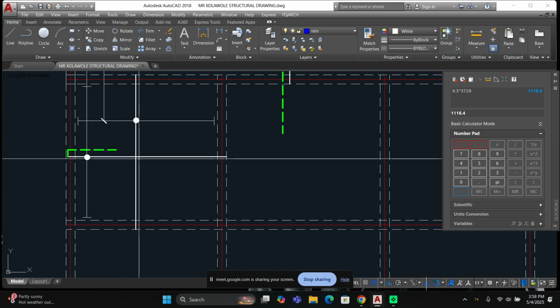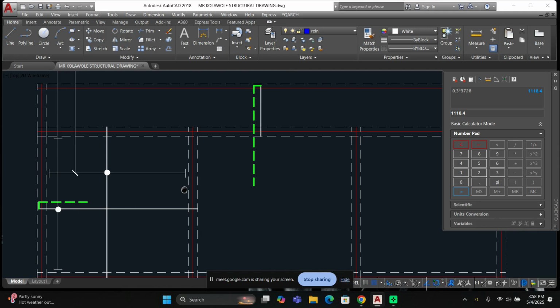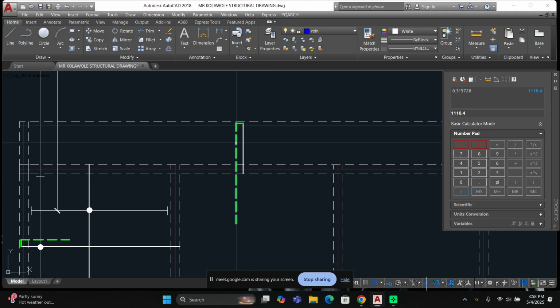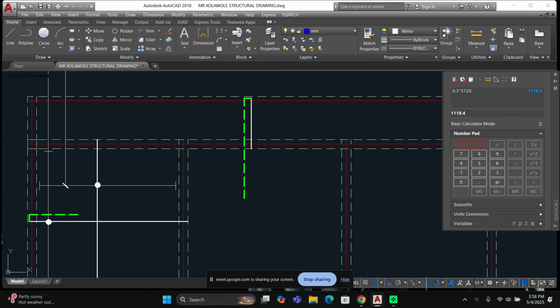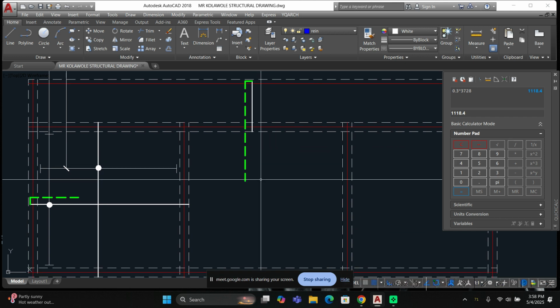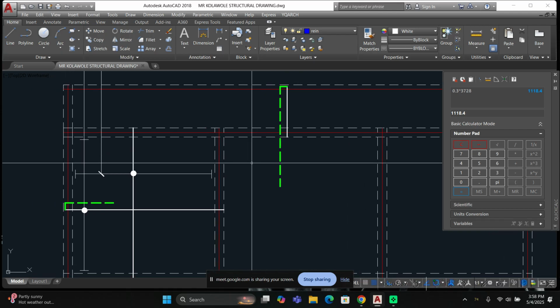Here now, this is not a cantilever slab, this is a solid slab. We have these two main reinforcements with the tick. But for a cantilever slab, it has to be inverse. So for a cantilever slab, the main reinforcement is the top reinforcement, not the bottom bar.